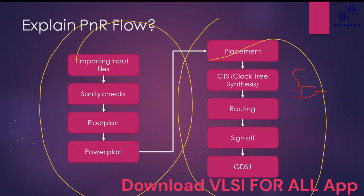After legalization comes scan reordering, which I will explain later in the slides. The tool does scan chain reordering. Why scan chain reordering? To make more routing tracks available, so that routing tracks are used more properly.